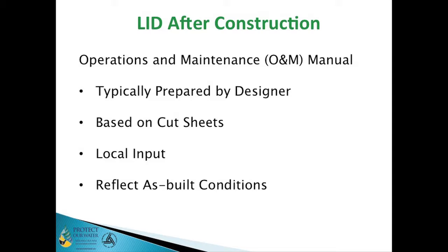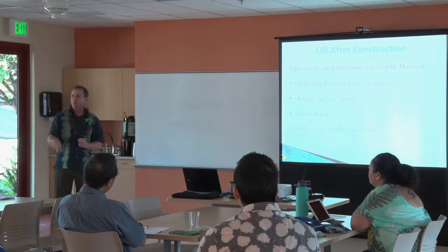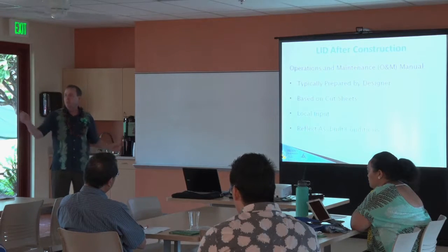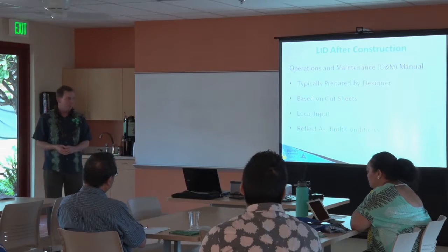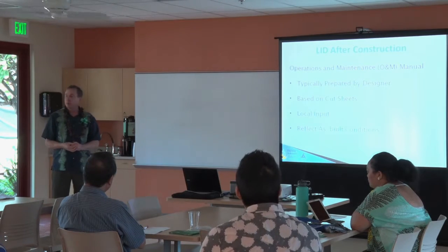If we were actually there when they build the thing, and we noticed 3 times during construction that we built these 6 bioswales, and this one right here just seems like it's getting a lot more water and a lot more sediment, and we keep having problems with it. So even amongst these, what we thought were 6 identical bioswales on this project, we may need to go back and revise that O&M manual and say, hey, the 3rd one here needs to be inspected every 2 weeks. The rest of them can be inspected quarterly or whatever it is. And some of this will change during the startup period and the contractor maintenance as we see how this goes.